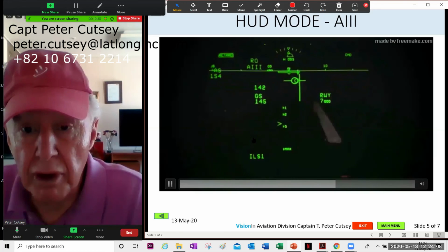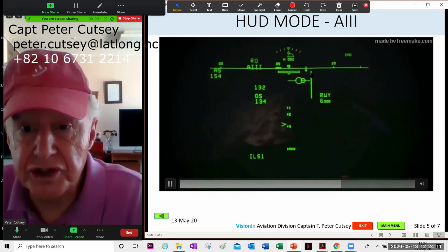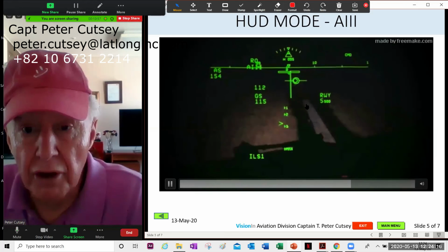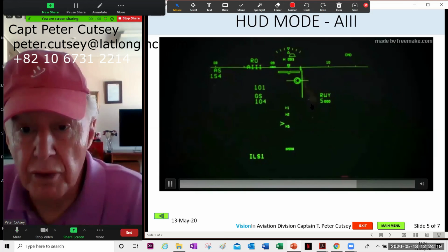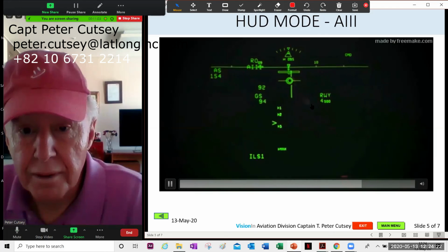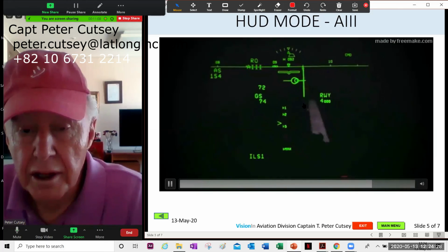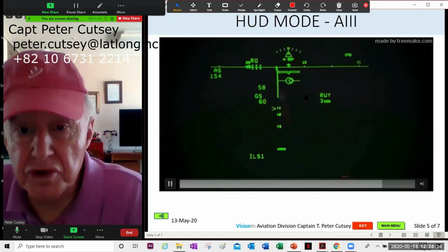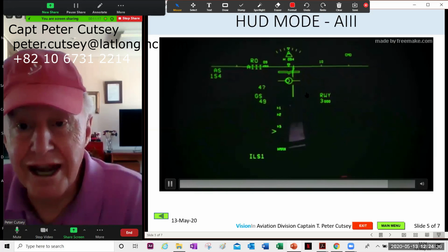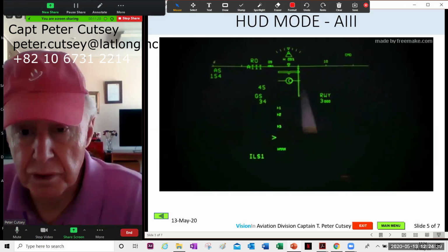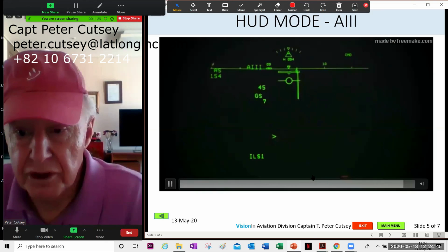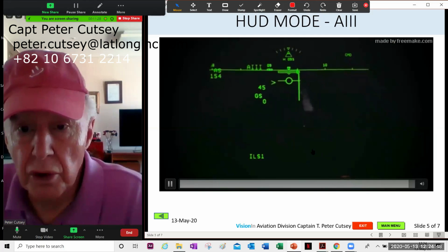There's the runway lights, there's the center line of the runway, which is generated from the localizer. And you're on the ground and coming back to the center of the runway. There's the actual ground speed. So there you are on the center line, looking good. So virtually, if you were in a smoke-filled flight deck, you could touch down using this technology without having to see anything until you stopped, if you needed to. The RVR here is 600 feet RVR in this particular case. So there you go. There you have it.